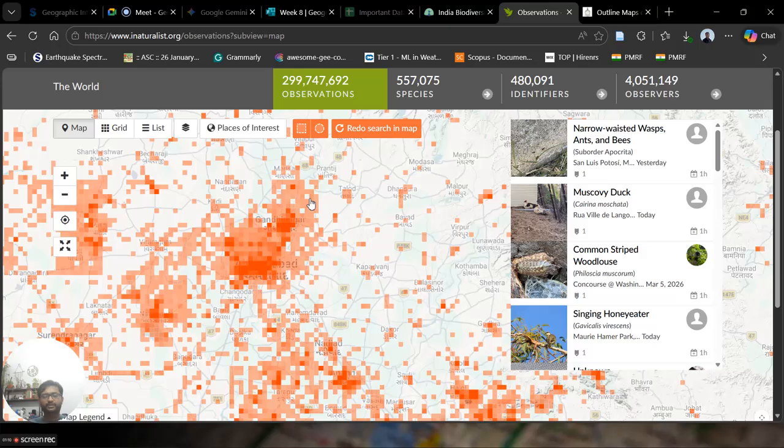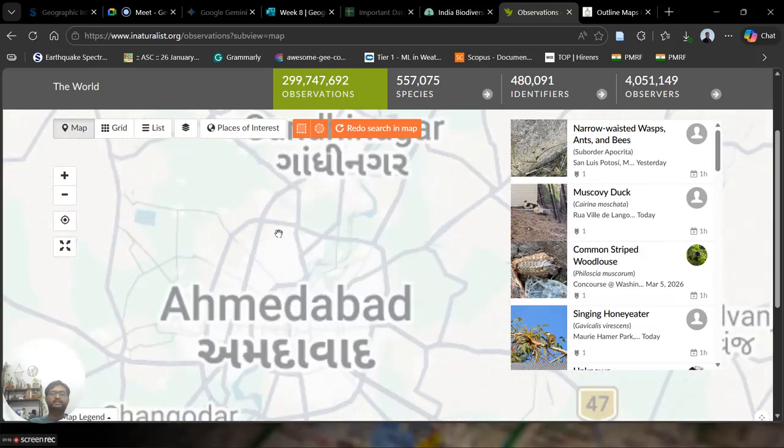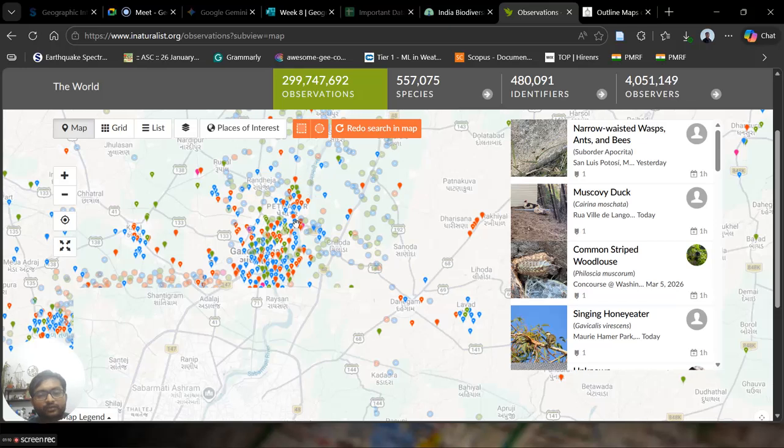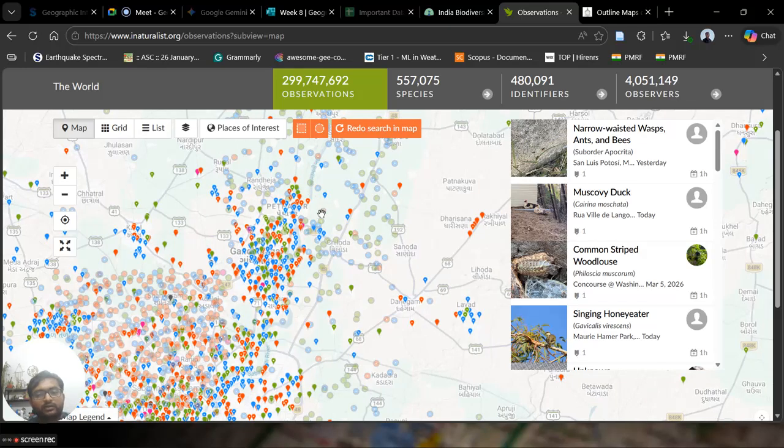What are pyramids? They are the different ways we zoom in, and according to that, how it shows the data. Basically, the idea is to load the data fast. So now you can see this is the final level where I reached. This data is vector data, but as you go to coarse resolution, this data looks like raster data. So basically, a kind of aggregation is happening with the zooming we are doing.